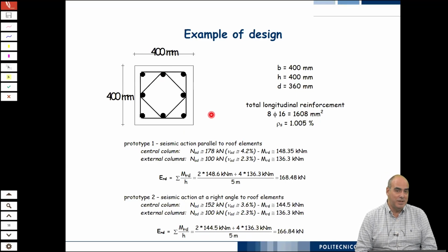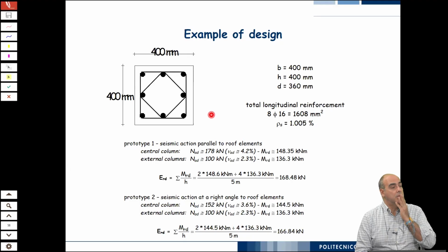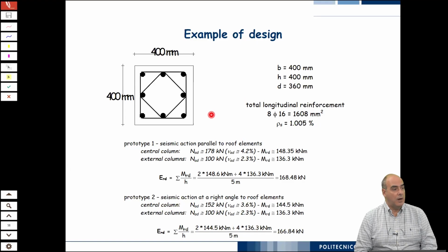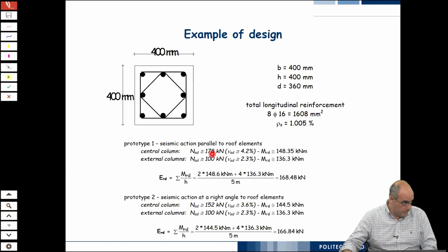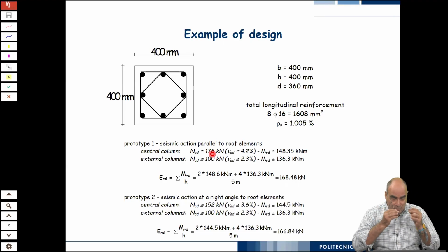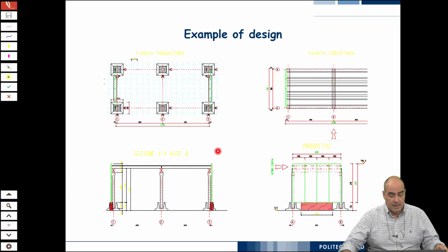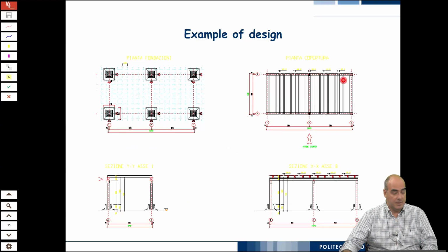This is not much different from what happens in precast building structures. We analyzed this mock-up building, and we calculated the load which goes on each single column. Well, you can see that the central columns take not exactly twice as much, but more or less like that, because you can easily figure out, if you have this building here, the beams are in this direction.